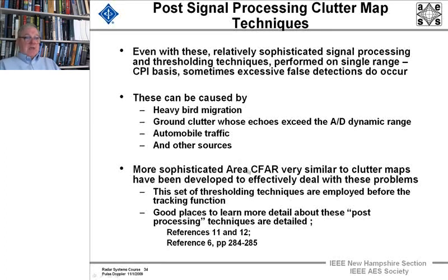And more sophisticated area CFAR techniques have been developed, some at Lincoln Laboratory, and those and others that Westinghouse did are in the ASR-9, and they are employed before the tracking function. Good places to learn about these post-processing techniques are in reference 6, these pages, and in references 11 and 12.